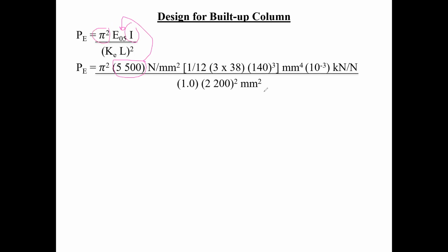Now, the moment of inertia, well, it's very simple. I have 3 studs, and they're bending about this. So this is the base. So there's 3 times 38. That's my B. And my height cubed is the 140. So that's the moment of inertia.